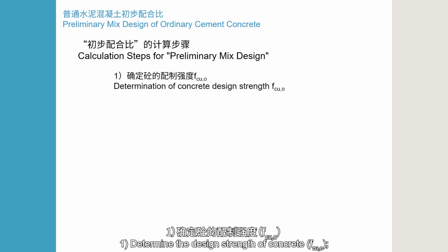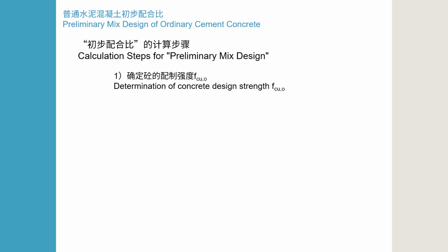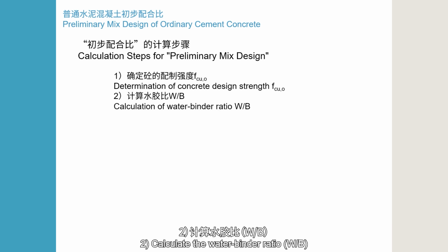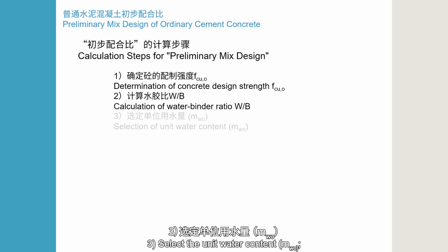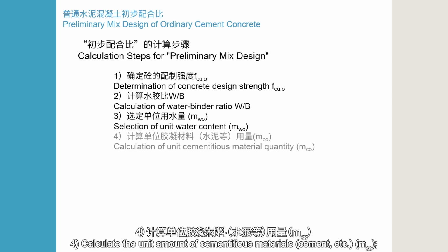1. Determine the design strength of concrete, FCU,O. 2. Calculate the water binder ratio, W/B. 3. Select the unit water content, MWO. 4.